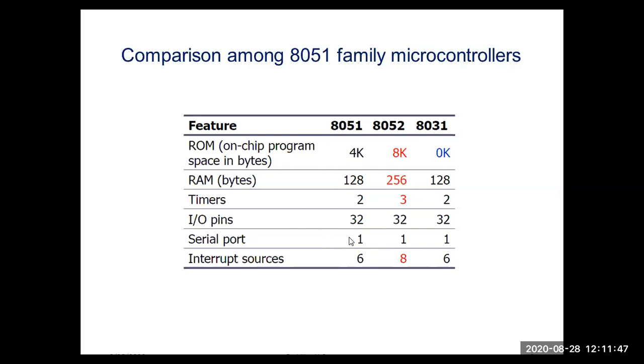Okay, application requirements means in terms of this feature: how much ROM, how much RAM, how many timers, how many IO pins, whether serial port is required or not, how many interrupt sources are required. According to that, you can select a particular microcontroller from 8051 family of microcontrollers.